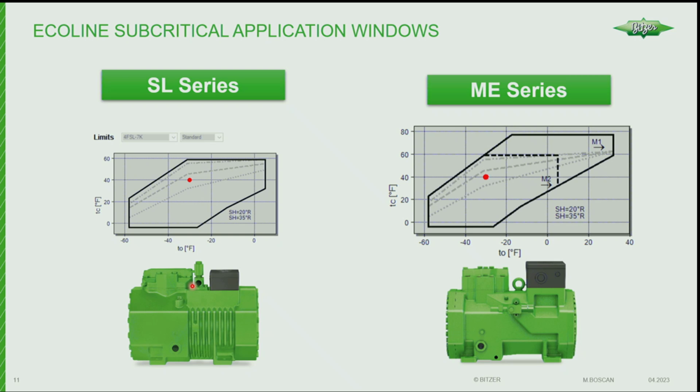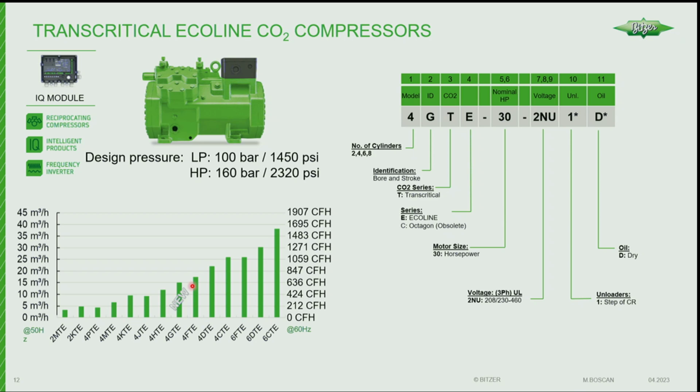On the transcritical, it is also a compressor protection. It's on the discharge side. So even if you close off the service valves, it's in play when the compressor's running, or when the compressor's valved off, because it's in the body of the compressor. It's on the discharge side.